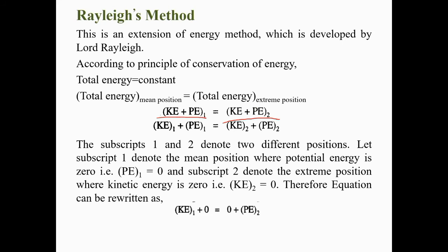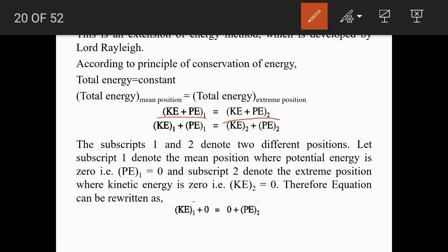Okay, same way potential energy, in case of a simple spring mass system, it is strain energy. Strain energy depends on the displacement from the mean position. If displacement from the mean position is maximum, then strain energy would also be maximum. We already know that at mean position the displacement would be 0, so potential energy would be 0, right? So potential energy would get maximum when it is at extreme positions, upper extreme or lower extreme during longitudinal vibration.